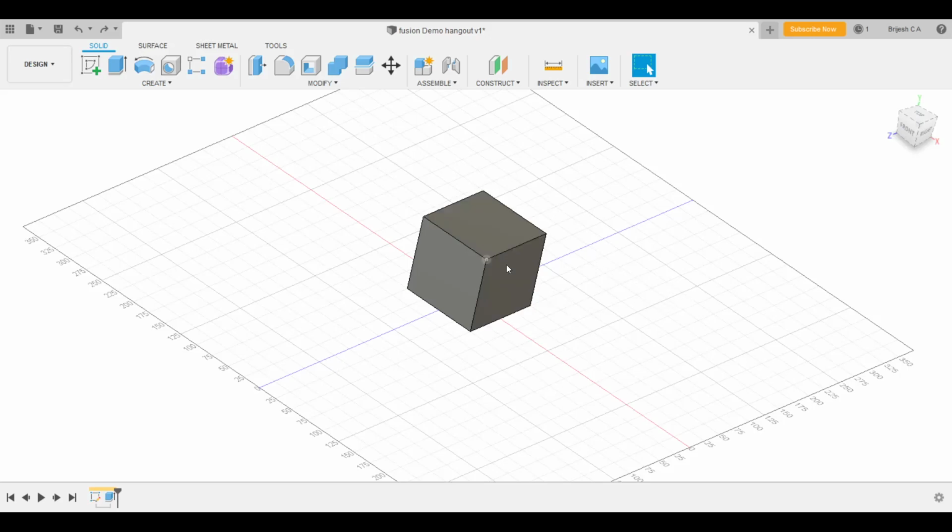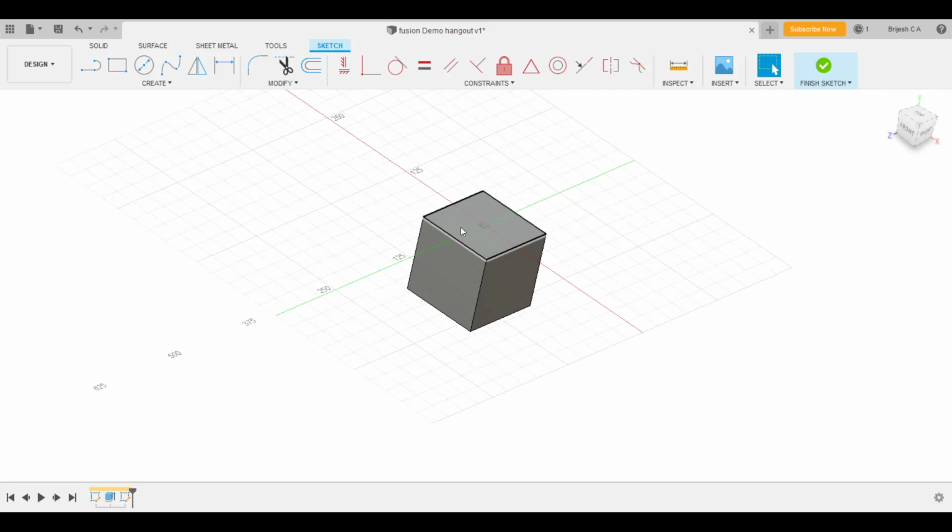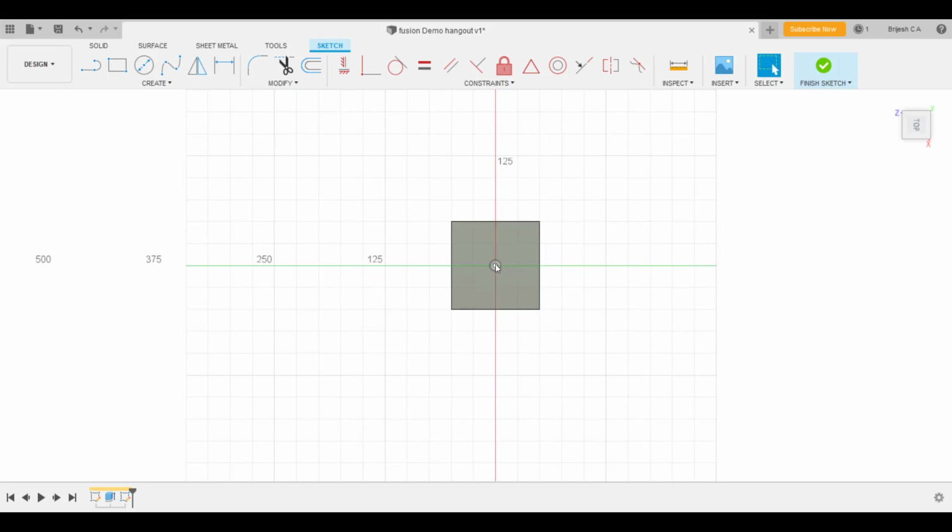If I have to create any sketch, any model, I have to create a sketch first. So we have to create a sketch. I right click on the surface or the plane on which I want to create. I'll say on this I want to create a sketch. Okay, which one? On this. This is the plane on which I want to create a sketch. Now for me, top view will give me an advantage. So then I click on circle. I want 50 mm and click OK.